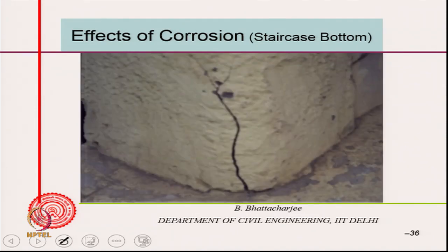This is an interesting case of a staircase slab, something like this. These people actually repaired it from the bottom by gunniting, and did not do anything else.